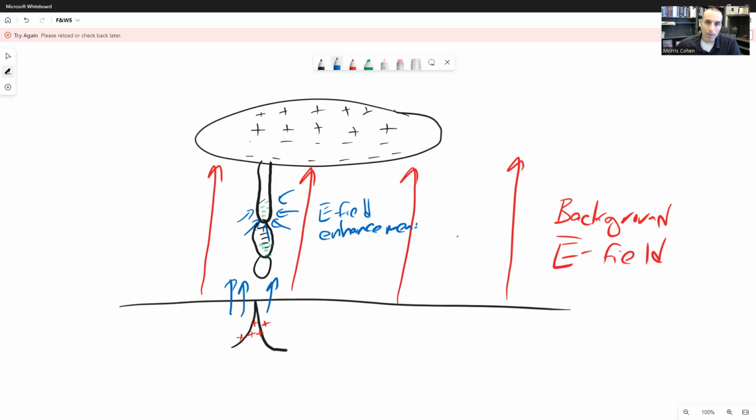And so now, eventually, you're going to get a process called connection, which is where you get a complete electrical connection from the leader to this lightning rod. And because the lightning rod is elevated, it's up in the air and it's very small, like needle-like, it's very easy to have a very intense enhancement of the electric field, and that's where this lightning leader tends to be drawn to. So that's how lightning rods basically suck in lightning, because the lightning wants to go where there's lots of charges to meet it, and any sort of point or tip of metal will do that.